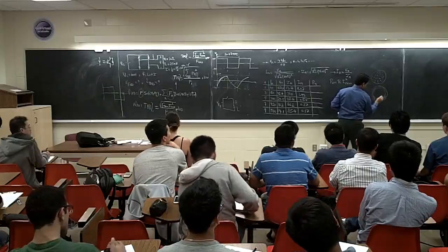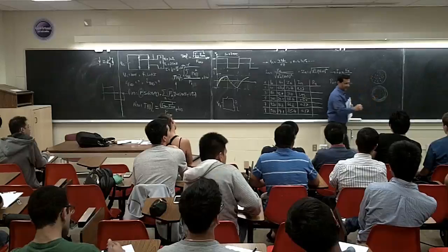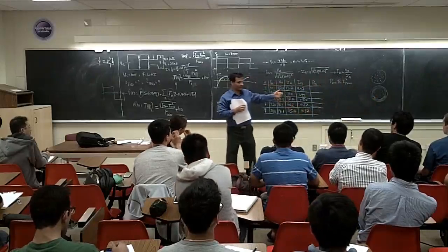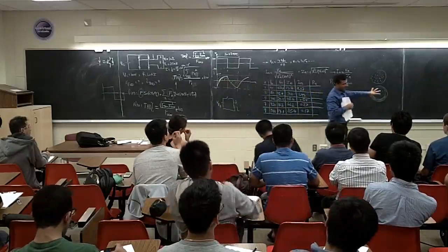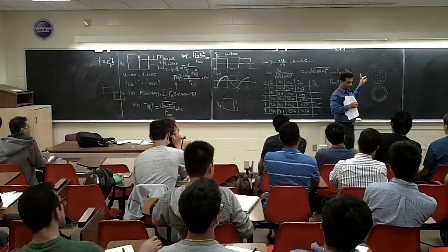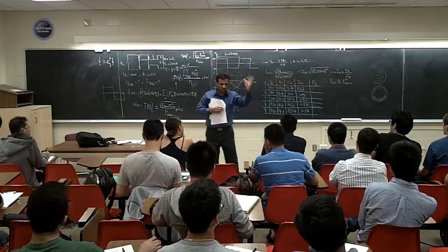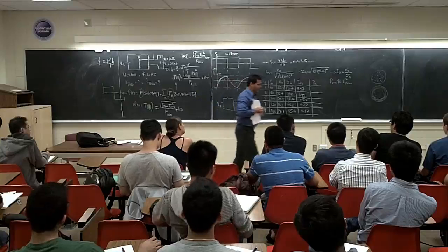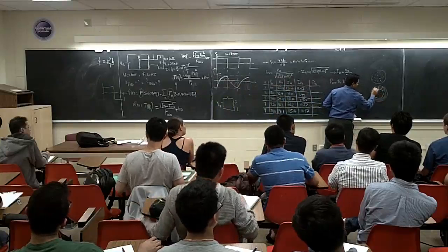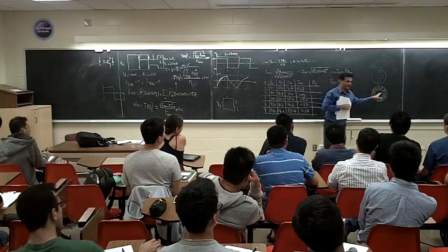They call it a skin effect also. Here we are going to have less. I can bring you one final element in case I modeled this one for an inductor. So basically, this way, if you look at it, the resistance is going to increase. When you have a high frequency current, the current tends to go through the surface of the conductor. So instead of having all this surface, it looks like you have just this surface. You know what I'm saying? You have a conductor with this much cross section, so this is less than this, right?